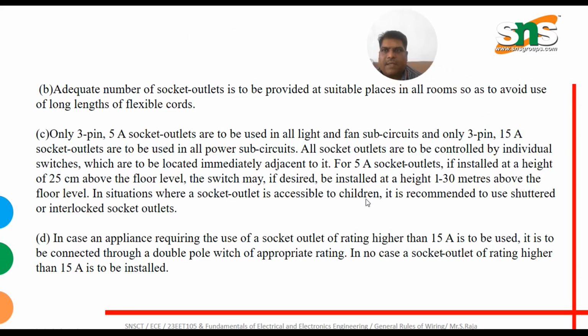The next is the important one. An adequate number of socket outlets is to be provided at suitable places in all rooms, so as to avoid the use of long lengths of flexible cords. Only 3-pin 5 ampere socket outlets are to be used in all light and fan subcircuits, and only 3-pin 15 ampere socket outlets are to be used in all power subcircuits. All socket outlets are to be controlled by individual switches which are to be located immediately adjacent to them.